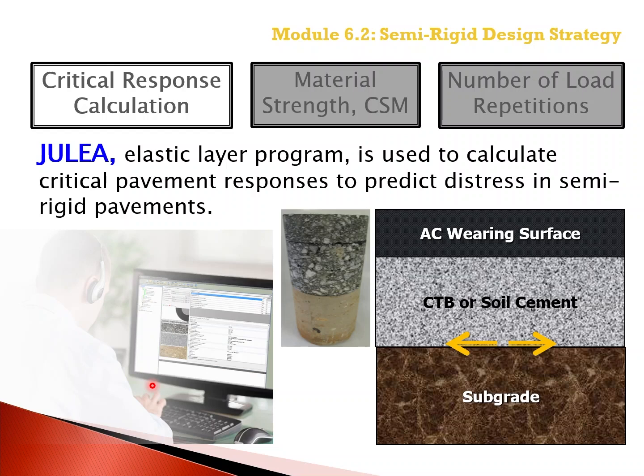So the JULEA program is used to calculate critical pavement responses for predicting the distresses, specifically fatigue cracking of the chemically stabilized layer itself, and that is the horizontal tensile stress at the bottom of the chemically stabilized layer.